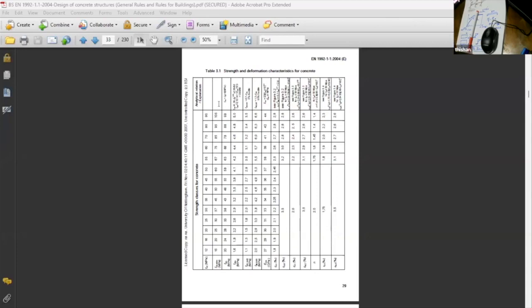Then we know for the specific rock available at that particular site, having its own peculiarities, we have calibrated the PDA by comparing the results of maintained load test and PDA. So once the calibration is done, your predictions from PDA will be for that particular site, and we can be sure what we are doing.